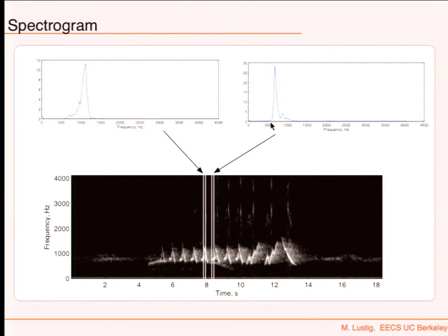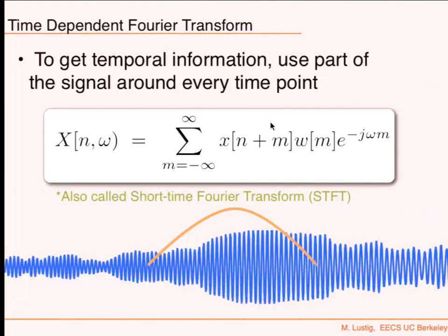Yes? When we define the window at the end, is n always at the middle of the window, or is it dependent on how we choose whatever window? So the windows we talked about before, it's the same windows that we did all this analysis on. We assume that these windows are real and symmetric, and they're about 0. Right? So the windows are about 0, either rectangular, triangular, Hamming, Hanning, Kaiser, Bessel, pick your favorite. Gaussian.